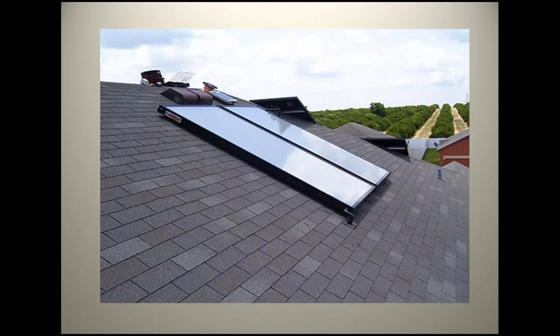Here's the photo, the PV that runs the pump in this particular one. So this is independent of the grid. So if the grid goes down for some reason, you don't have a pump that isn't pumping and collectors that are then getting hot. And that's a pretty good solution because if it's sunny enough for the PV, it's sunny enough for the solar hot water. So those go together pretty well.